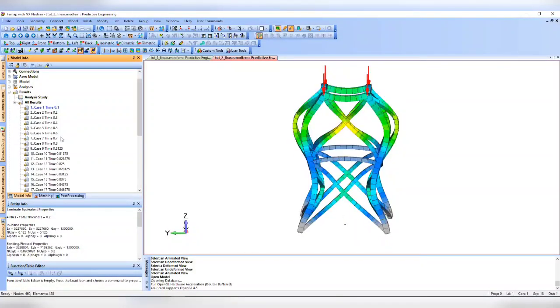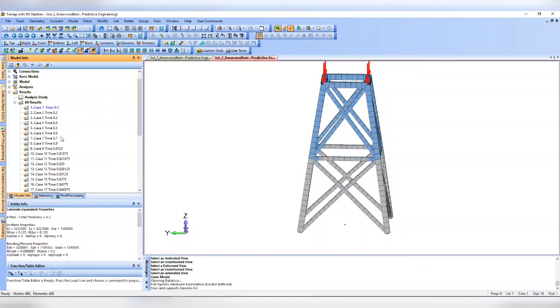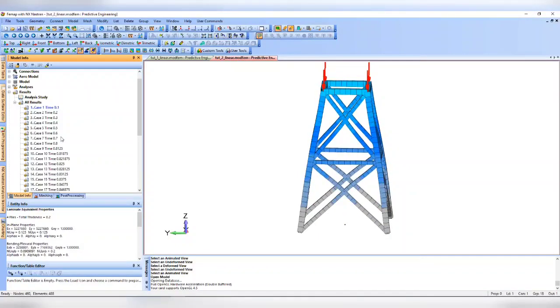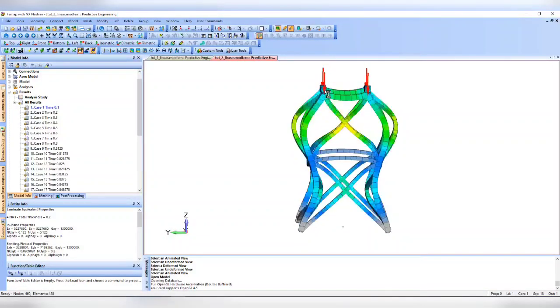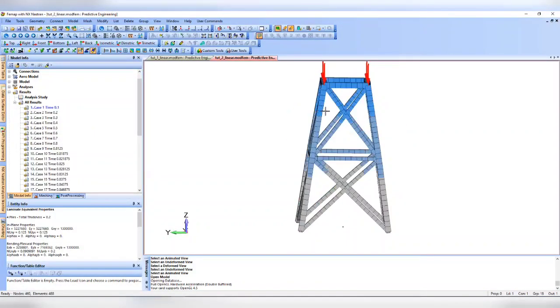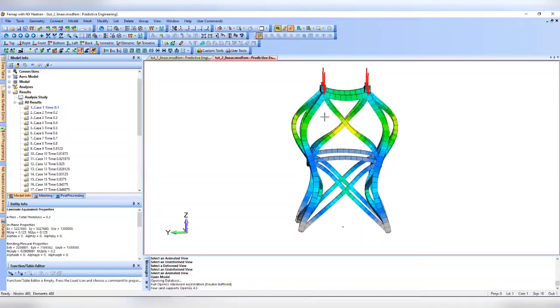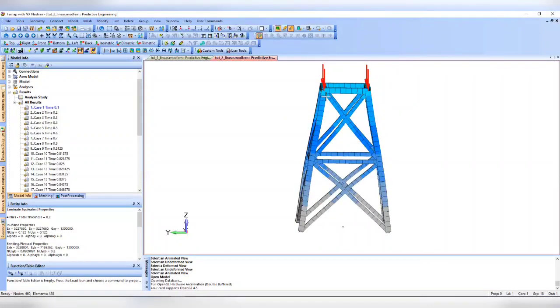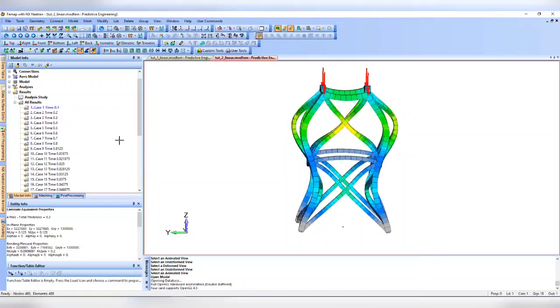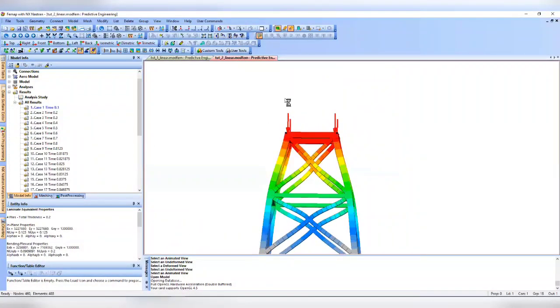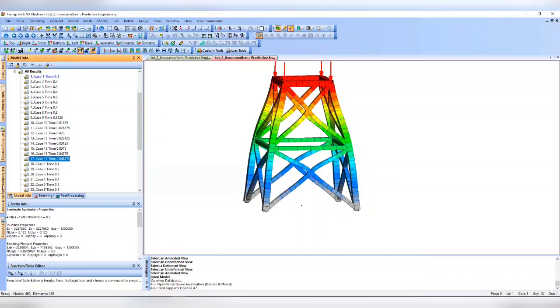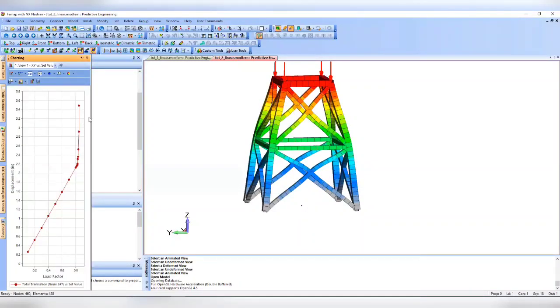If you were just to apply it all at once, you wouldn't be able to capture all the details of the large displacements. That's why you have to apply it in smaller increments. That's what you see here, it's being applied at 10, 20, 30, 40. It's moving kind of fast, but it's being applied in increments, 20%, 30%, 40%, 50%. And then finally, the solution starts to go unstable at around 84%. And we can actually chart that.